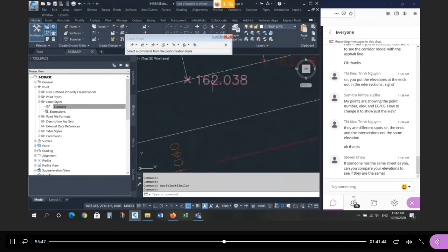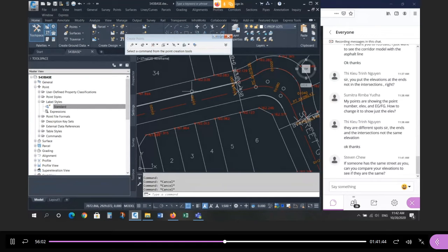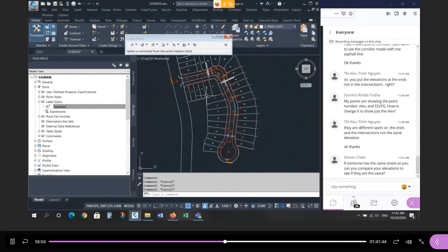If you had to calculate these one at a time on paper, from AutoCAD you can get the station value of this point from the horizontal alignment. Then you can get the elevation of that point from the profile, and then you can figure out how to go from the center line down the pavement to the gutter and up the boulevard to get that elevation. Imagine doing that calculation for this entire site all the time. So that's the advantage of this technique.